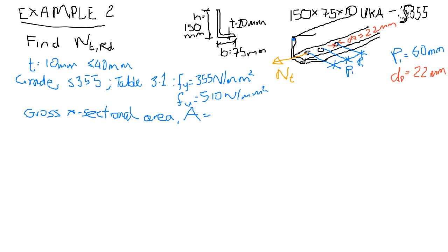However, it's a rolled section, there's actually a little fillet radius in here, so it gets a little bit thicker around the corner, and there's a little drop-off on both ends there. So that wouldn't give us the exact area, but it gives us an approximate area if we multiply 150 by 10, and then 65 out here multiplied by 10. But there's a little fillet. So we take the 150 high, multiply by the 10 wide, which gives us the cross-sectional area of this bit.